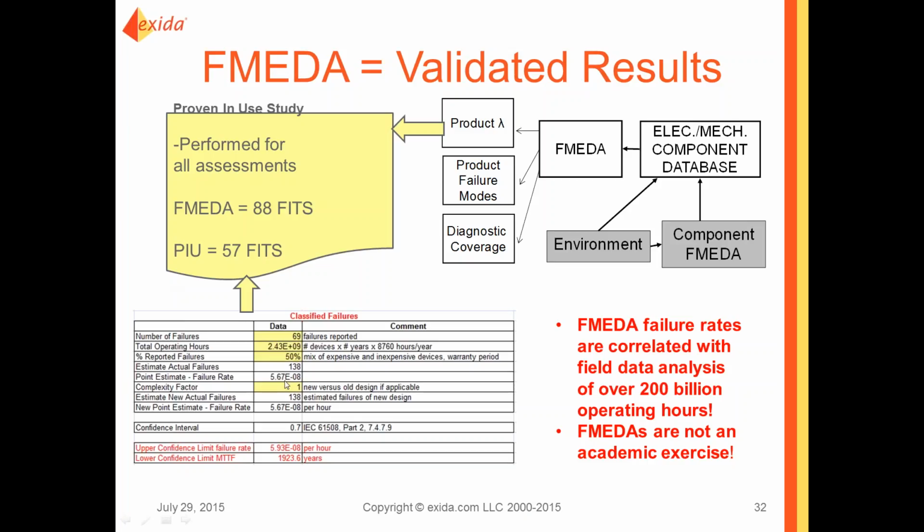In this one, there were over 2 billion hours of device data. We had failure rates and failure modes for the field study. The proven in use analysis would say this device has a failure rate of 57 FITs. The FMEDA predicted 88 FITs.